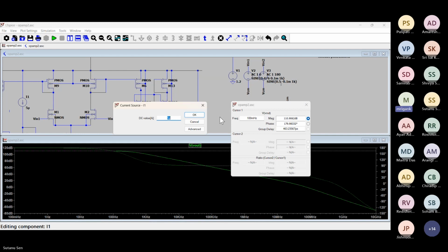So here, this is 10 power of 4 gain, which is pretty high. Generally, for this kind of front-end amplifier, at max we will need 80 dB to 90 dB gain. So here, if you want to improve the bandwidth, there is an opportunity. You can sacrifice the gain and improve the bandwidth a little bit. But for the time being, you can just try to confirm.